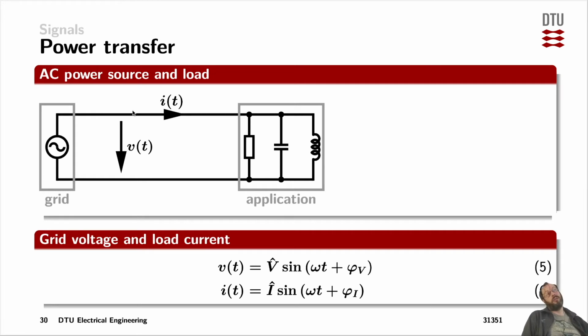we've got the voltage across the lines here, and we have the current defined as a positive value towards the application and then going back again. Now, once you've defined the direction of a voltage or a current, it is as it is. You can run all the math on it afterwards, and if you figure out, oh, it was supposed to be negative, I defined it the wrong way, that's totally okay.